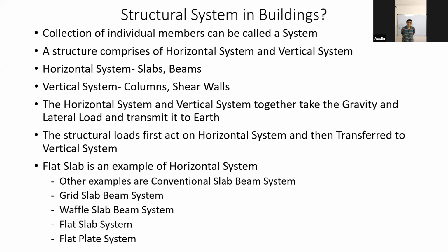Bracings, Mr. Chirag is saying, but bracing in itself cannot be called a vertical system independently. It generally forms a part of some other structural system. So we will not call bracing an independent structural system. And bracings we generally do not provide for taking vertical loads. Yes, they may take vertical loads because of their geometry and placement, but generally they are not intended to take vertical loads.